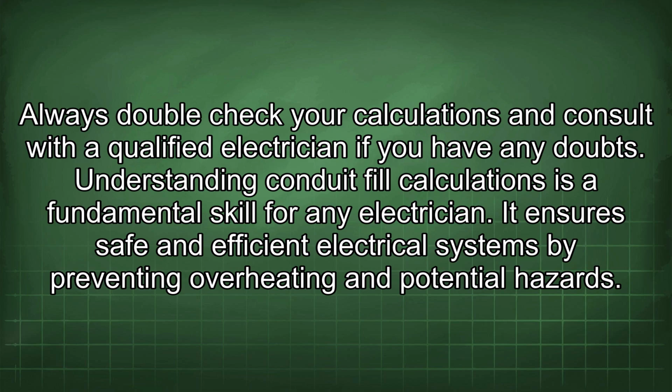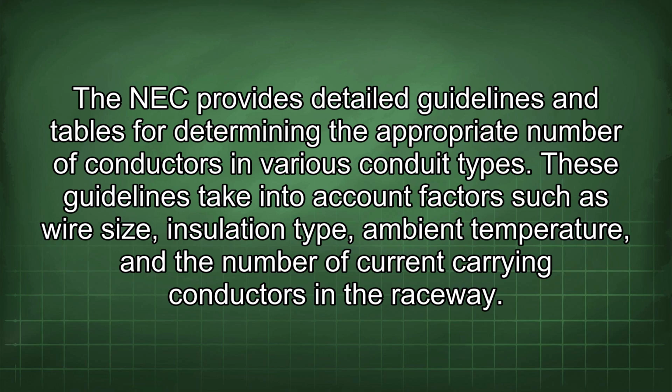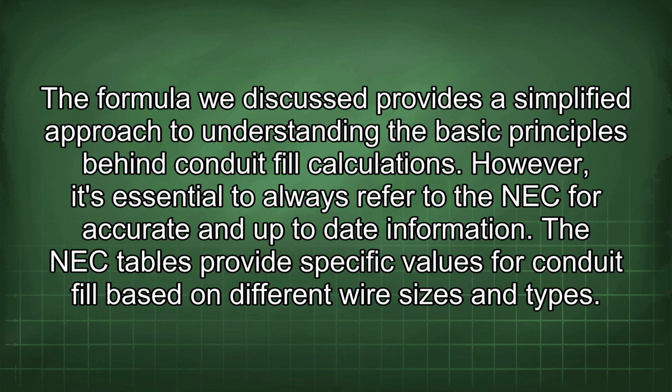Understanding conduit fill calculations is a fundamental skill for any electrician. It ensures safe and efficient electrical systems by preventing overheating and potential hazards. The NEC provides detailed guidelines and tables for determining the appropriate number of conductors in various conduit types. These guidelines take into account factors such as wire size, insulation type, ambient temperature, and the number of current-carrying conductors in the raceway. The formula we discussed provides a simplified approach to understanding the basic principles behind conduit fill calculations. However, it's essential to always refer to the NEC for accurate and up-to-date information.